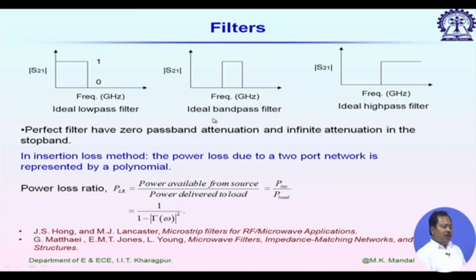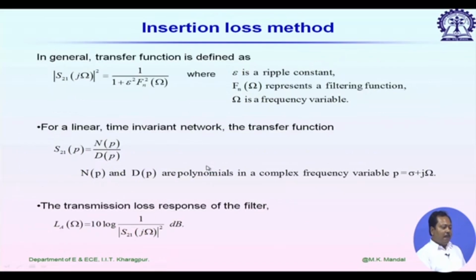For example, if we have to design a band pass filter, then in the pass band it will have good impedance matching with the source and load, and out of band the impedance mismatch will be as high as possible. This is done by changing the S parameters of the component we use for filter design.